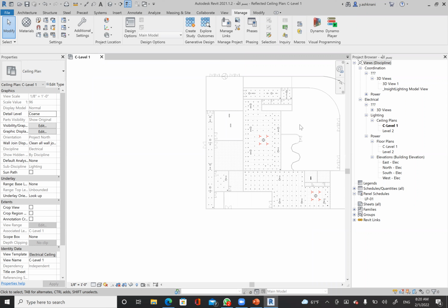So sometimes when you change the location of the architecture linked file, the PC will not be able to identify that file. If you change the name or the location, the link will be broken. So you can just go to Manage Links and then Reload From. If that file was added already before, you just have to reload from. That's okay, right? Okay, yes.